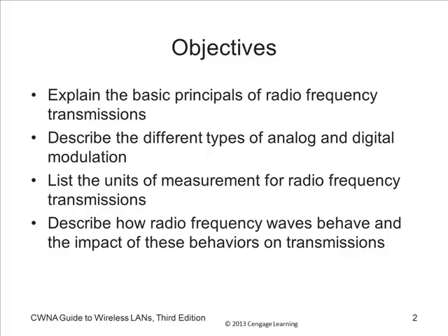Units of measurement in radio frequency transmission are going to have absolutes and relatives, and the relatives are what we're going to use most of the time. We're going to call that dB, and then we're going to base it on a milliwatt, call it dBm. So don't get too hung up on that. And there's an exercise. The rule of tens and threes is a quick way to do the calculations of how much signal strength you're going to have based on what happens in the path. It's not precise, but it's quick.